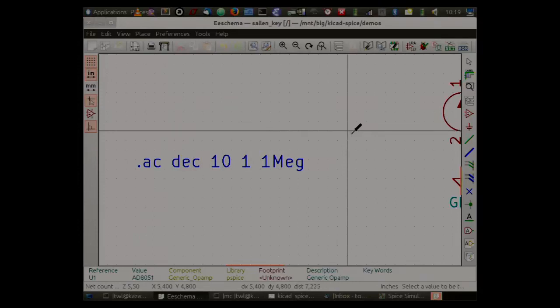This heavily depends on the library managers. Wayne, would you like to add something? Just on that topic, it falls in the same scope as the classic atomic symbol, where we have a fully defined part number, and if people provide them, then we would have them for our libraries. But there's thousands of op amps. We have a common op amp symbol, so you're going to have to go find the SPICE model and then add that. That would be outside of the scope of our normal libraries.